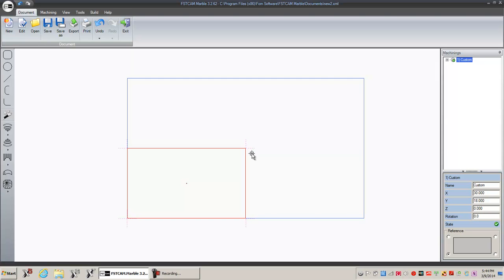With an 18-inch diameter blade, it could be approximately 5 inches. So if I wanted to draw another part, I would need to leave 5 inches between them. Well, I don't want to do that. I'm wasting a lot of material. I would have to start with some type of optimization. So I wanted to talk about that now.